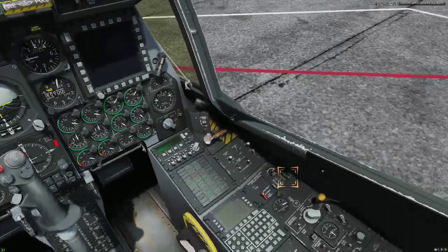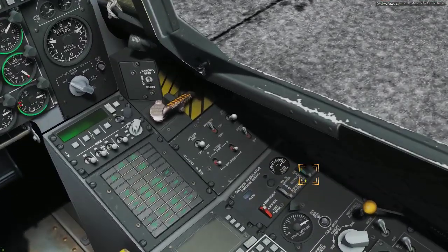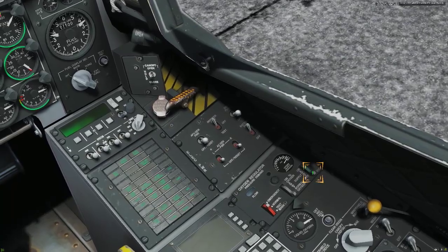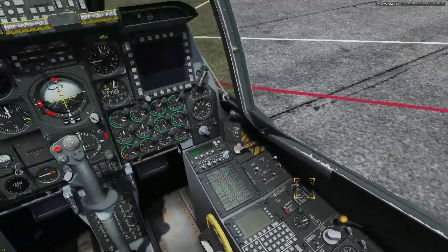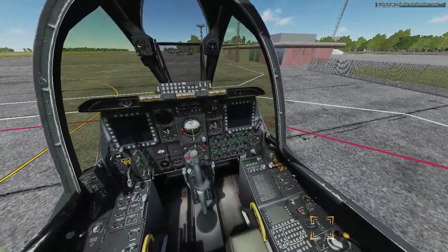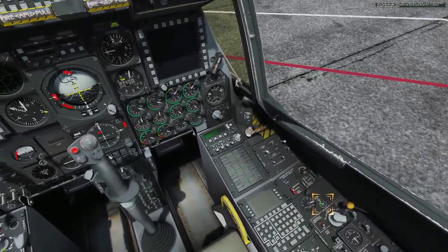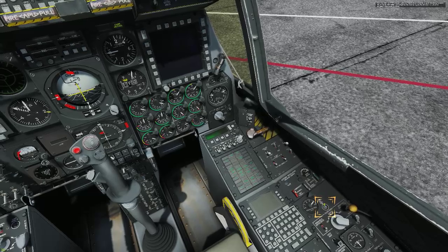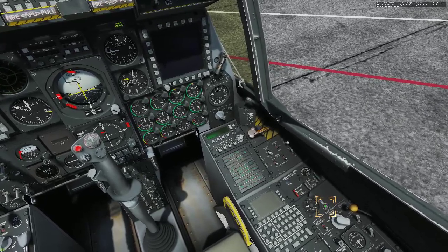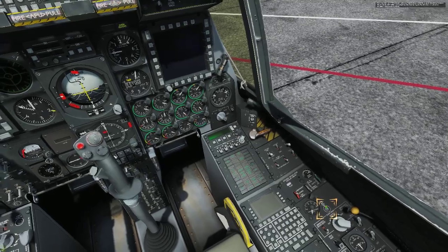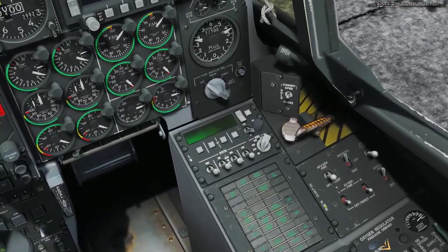On the oxygen regulator panel, set the supply switch to on, and check for oxygen flow to be indicated in the flow window. Press the Oxy-In Test oxygen indicator test button to test the oxygen remaining indicator. Watch the Oxy Low caution light on the caution lights panel to turn on when the indication falls below 0.5 liters.